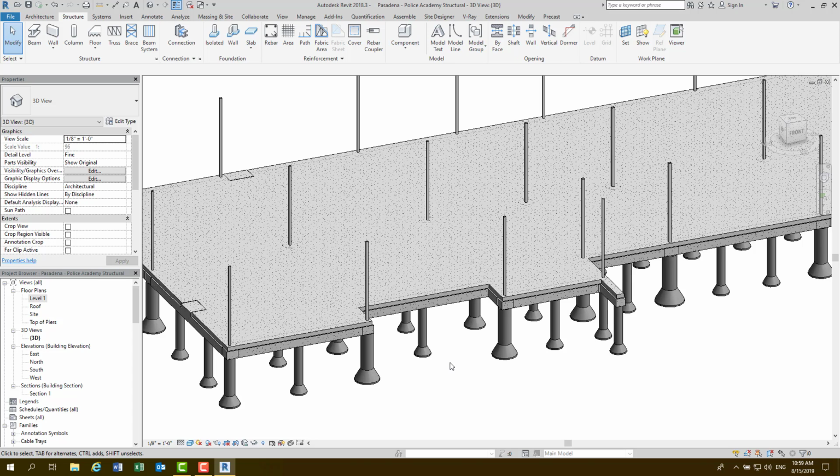Okay. So we also have some other HSS tubes that are also going to be used as structural members, so I need to grab those as well. So 16 by 4 by a quarter. And then they've also got 14 by 4 by a quarter. And I think that's it. And then they've also got some K-series joists that I need to grab as well. So let's go ahead and write those down. So they got 28 K9s.